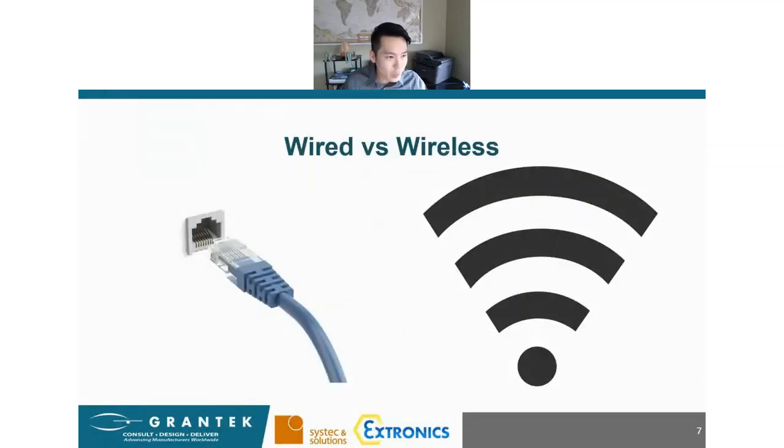All right, so I do want to talk about just kind of background of the history of wired networks into wireless. So wired networks have been around for quite some time now, and whenever you need to integrate field components to control devices, you would start with using a wired connection. There are a number of protocols out there, things like Modbus RTU, DH+, Rio, and they have started to transition over to Ethernet-based protocols, so Modbus TCP or Ethernet IP, etc. The technology that came before wired Ethernet, so it took some time, but wired Ethernet now is the prevailing technology.